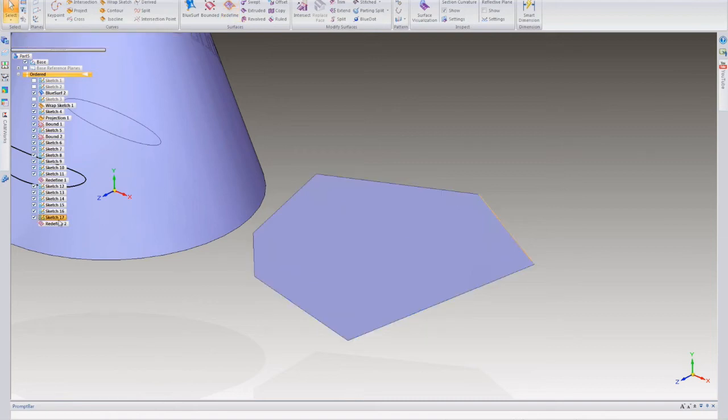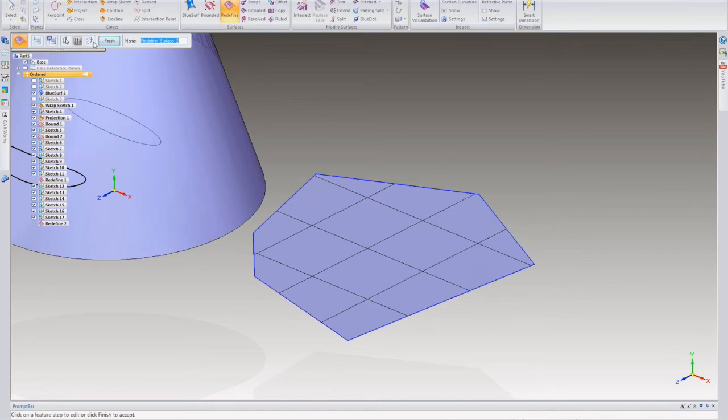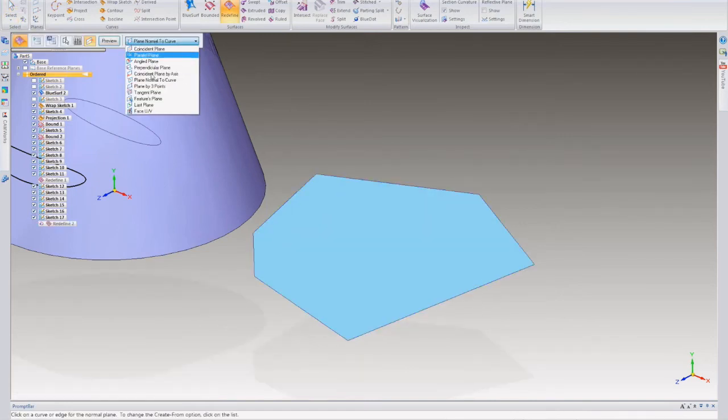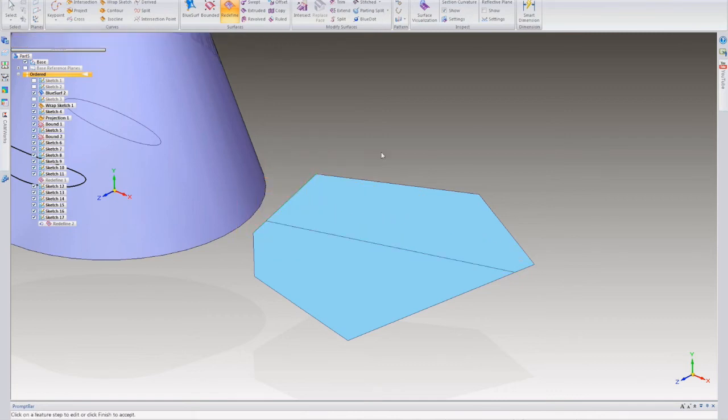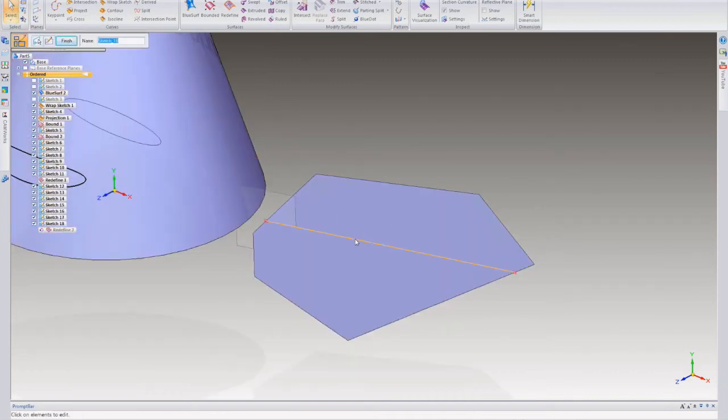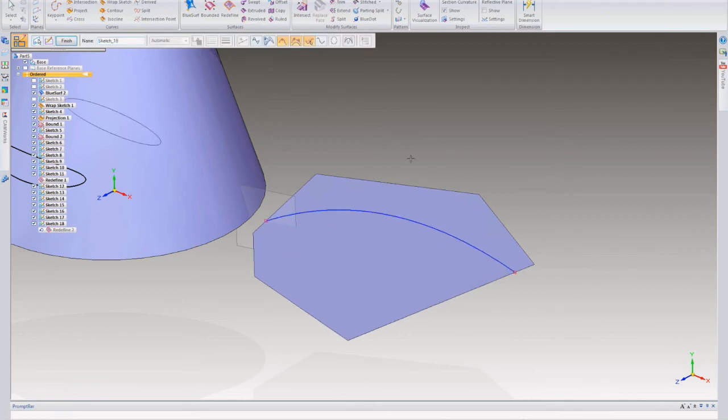So as you see, it actually places a sketch. I actually didn't go ahead and accept it. Apologies. Let me just do the single. I like plane over the curve. Let's grab a sketch through there. There we go. That's what I was looking for. Since this is ordered, it creates a sketch before this, so it creates a correct order history. Now I can dynamically edit that surface.